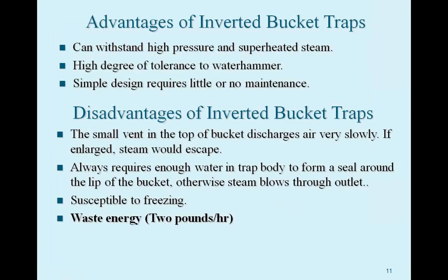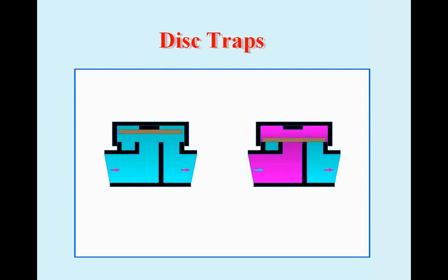So you think about that, over the course of a 24-hour day, you're using close to 50 pounds of steam if it's operating at peak efficiency. And that's an important consideration when you look at how many traps do I have, how often do they work, and how much steam am I using just to operate that trap.